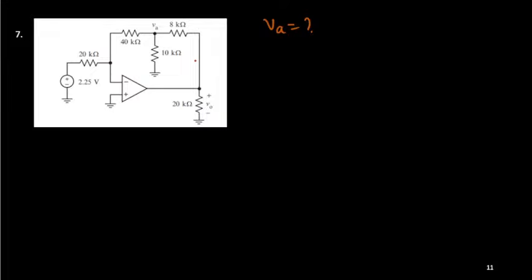Yes, that is the question. How to find the RF in this circuit? So two ways you can do this. You can convert this T network to a pi network, or star to delta conversion. That is one possible way. Another one, without considering this, you can also find it.